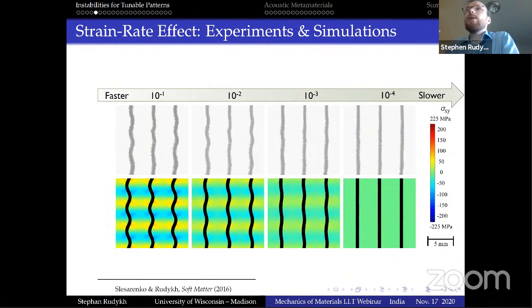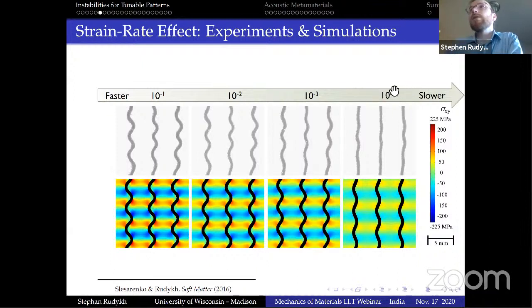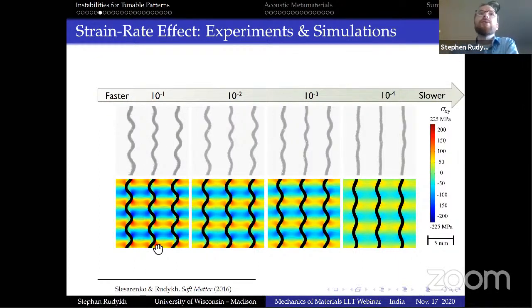So we also can model this, of course, in finite elements, although viscoelasticity is quite a tricky subject, and there are many constants that may not be easy to capture very accurately, but this way or another we can also obtain the information numerically on what happens locally in terms of stresses and how they relax, etc. So we can also continue further to show that, of course, the same sample that we load slowly will still buckle. We just need larger strains for that, and for the faster loaded one, we already have a very well developed pattern that also can be predicted with numerical analysis as well.